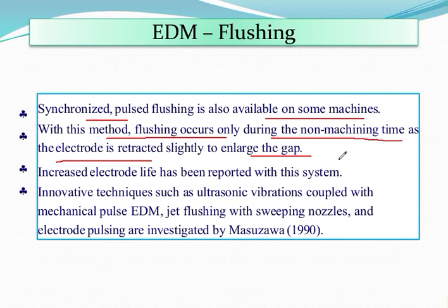Innovative techniques such as ultrasonic vibration coupled with mechanical pulse EDM, and jet flushing with a sweeping nozzle and electrode pulsing, were also investigated by the researcher Masuzawa in the year 1990. So these are the upgradations or developments that have already taken place with the EDM process.